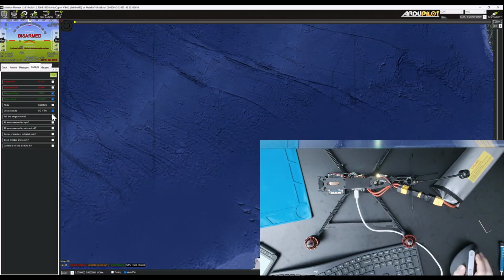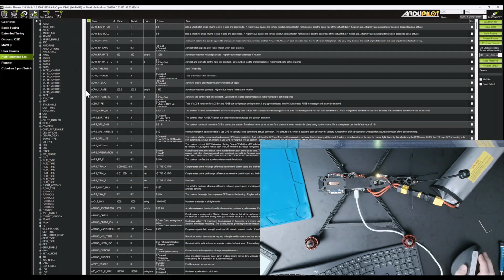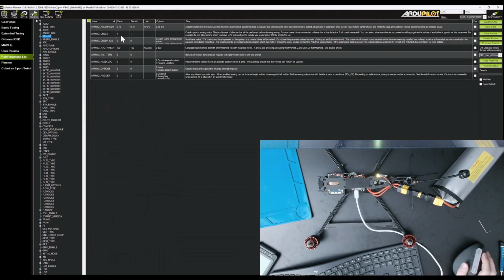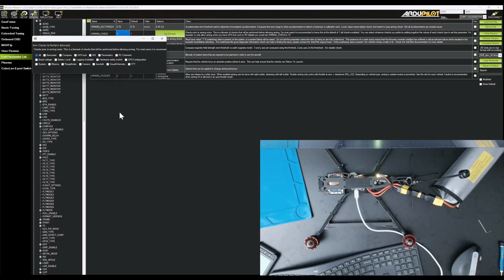You can see all the checks that we are going to validate prior to flight. And let's arm again. And we can see another message related to logging failed, and we don't have logging at all. Yeah, so we can disable logging. Or alternatively, we are going to go into config and look at arming parameters. And there is arming check. Arming check by default is all. And you can see there are many different parameters, including logging availability and GPS. And in fact, we don't need logging, we don't need GPS.